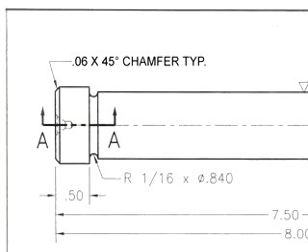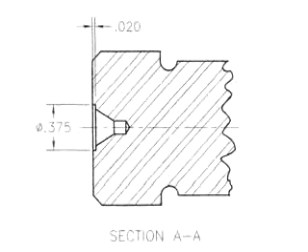In this example, the direction of the arrowheads on the section lines indicates to us that the viewer is positioned on this side of the part and is looking at the section in this direction. And here is our section view, section AA. Well, it's AA because our section line was identified as AA, not because it has a drinking problem.